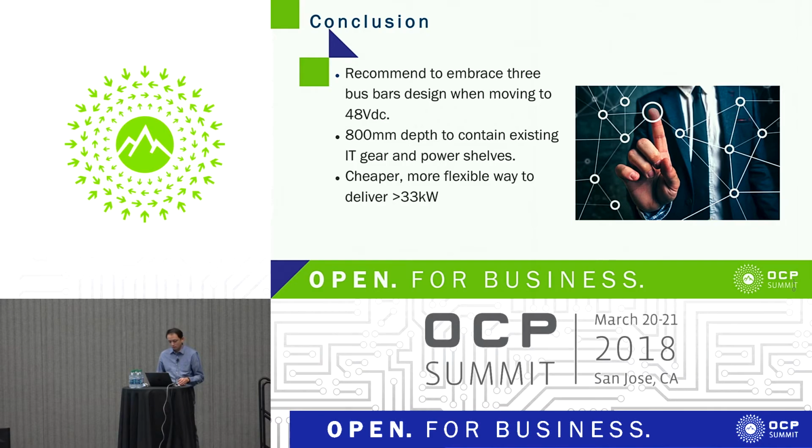Wow, this goes fast. So for the quick conclusion, we recommend to still embrace the 3 bus bar design when we move to the 48-volt DC, because we think that's the most convenient, flexible, and higher capacity design. And in our proposal, we will continue to use the deeper depth, the 800 millimeter one.